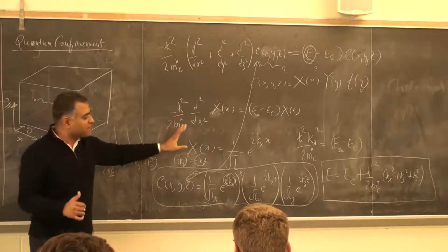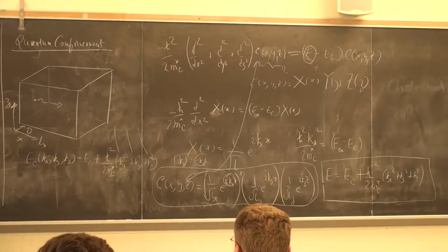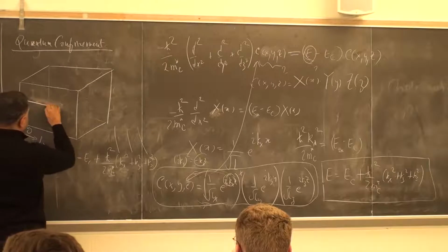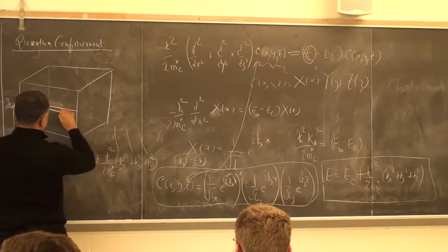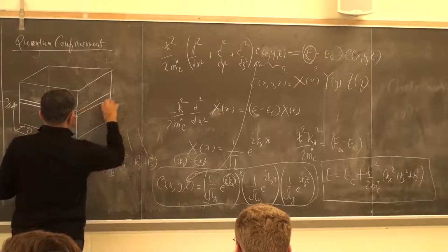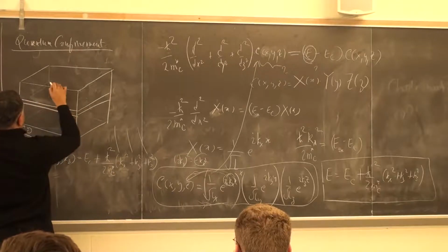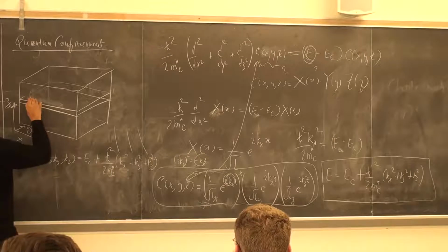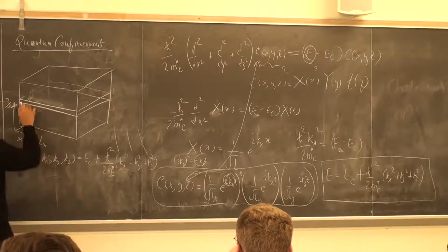All right. So now what I'm going to do is, instead of having the electron be free in all 3 directions, I now put in a very thin quantum well in this structure. And physically, what does that mean? It means that I'm going to have, let's say, a few nanometers, 2 or 3 nanometers of another semiconductor